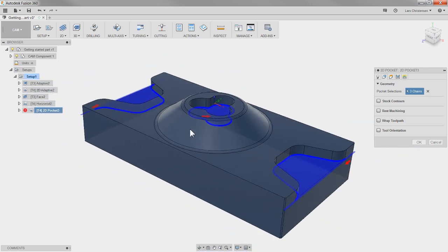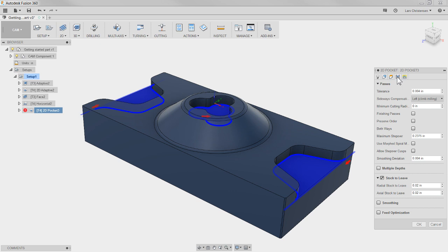That is perfectly fine here. A couple of points to point out on this toolpath, I think, is important: you can control your maximum step over to whatever you want. So this is a 1/4 inch end mill, so 0.25. That would probably be my default.